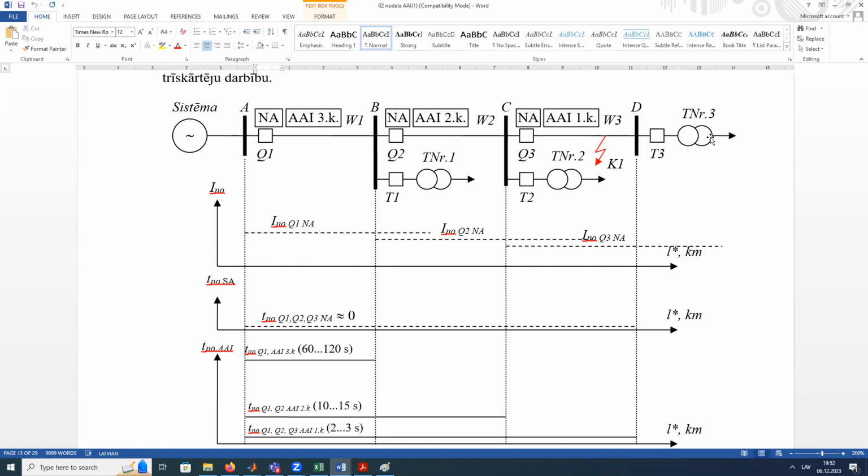Yeah, so via electrical motor, when we have a power supply, we store this mechanical energy into a spring. Then in case of fault, this spring gives enough kinetic power to disconnect the line. I think it is clear. In this case, when we have only spring energy, and we don't have any power for additional reclosing, there could be one more type of operation when we use series reclosing. I'd say an ugly way of reclosing, but it is due to a very cheap solution without investments.